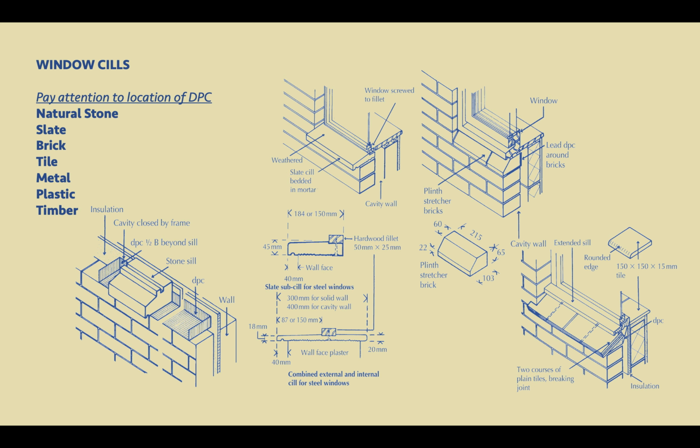Considering the waterproofing purpose of the sill, it would be important to pay close attention to the location of the DPC and other kinds of details that help take the moisture or water away from the opening. Once again, do not bother to remember the sizes, but they will help you understand exactly how these things are put together in a window assembly.